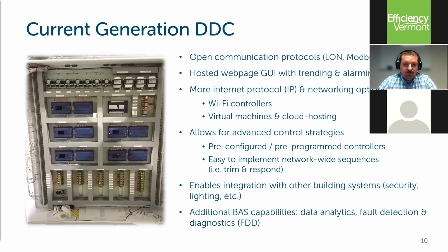You can upgrade to it easier. We also have better control sequences that we can do now. A lot of the manufacturers started having ASHRAE standard programming sequences already implemented in them. So now instead of writing a program from scratch, a lot of the times they came with the programs you needed and you just need to configure it for your specific application. It made it easier to also deploy these controls. Now you had options for mass downloads and mass edits. So now your contractors and your programmers can easily set up very, very large systems quite quickly.